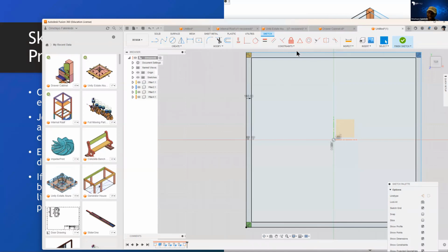To do that, we can do what is called an extension. We can extend this line beyond where it is to join this line. If we extend all our lines, we will see that all the pillar areas will be omitted. So I can choose modify, extend, and once I extend this line, if you look carefully, you'll see that there's a red finish in there. If I click it, it has extended that line. If I also try to extend this one, it has extended that line.